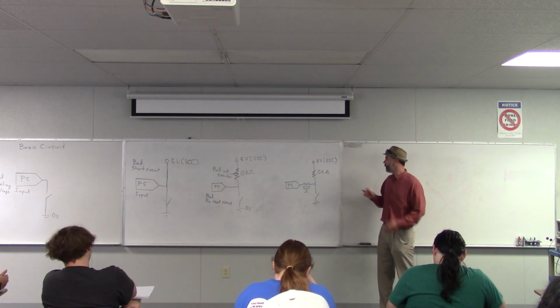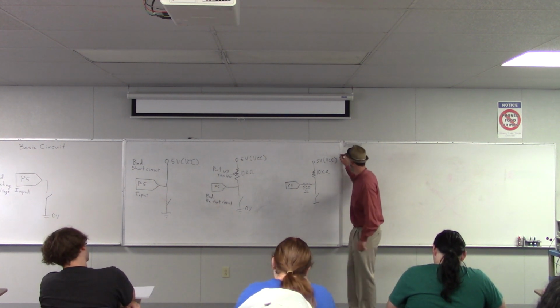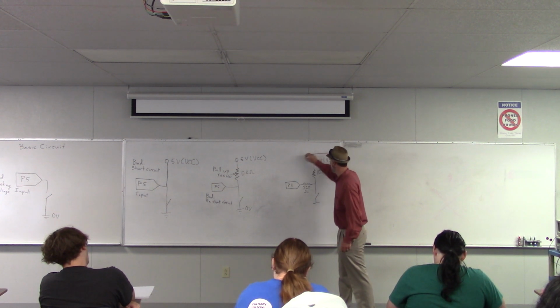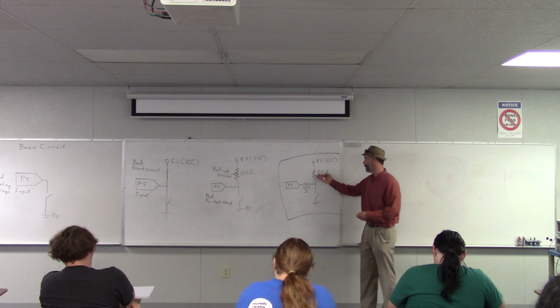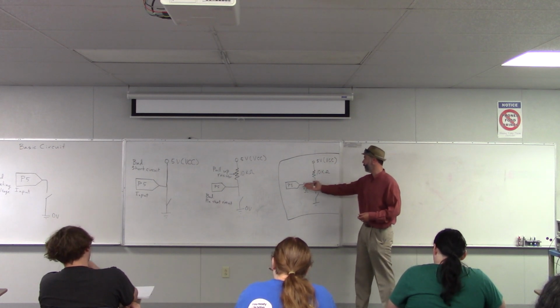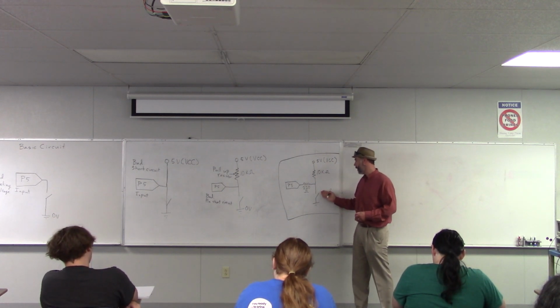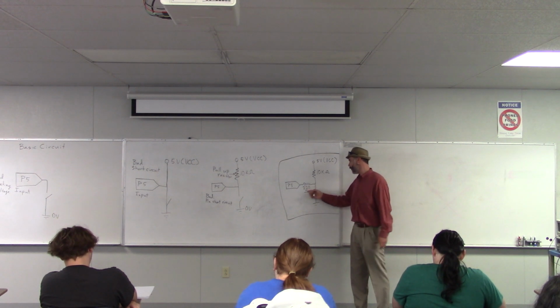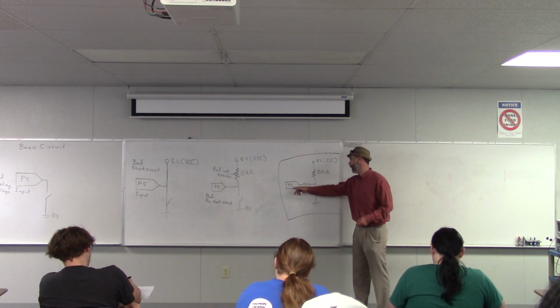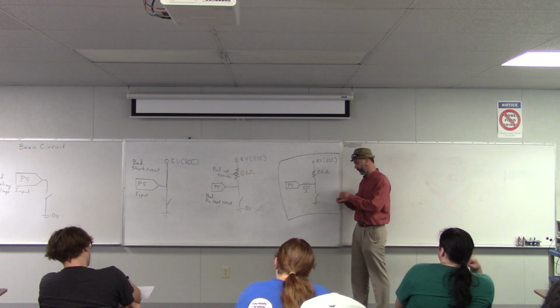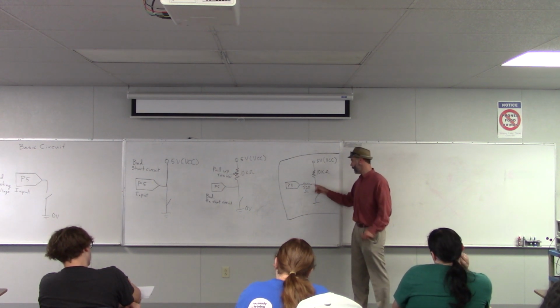So this is the final circuit that is used for our whiskers. Okay. So the 10 kilo ohm resistor pulls up that pin voltage when the switch is open. This 220 ohm resistor protects the pin if it's used as an output, and then the switch, when it's closed, pulls this pin voltage down to 0 volts.